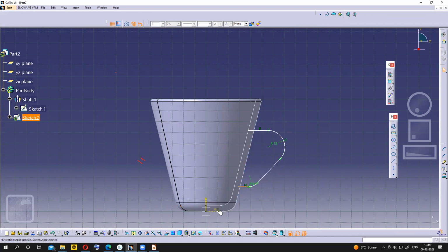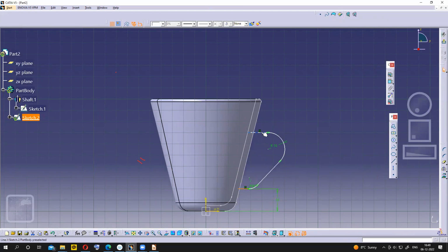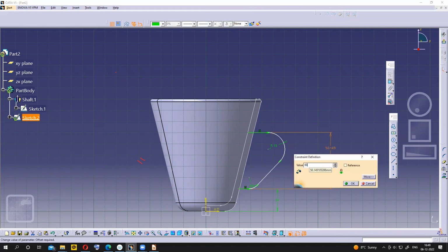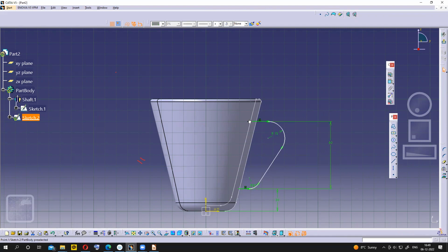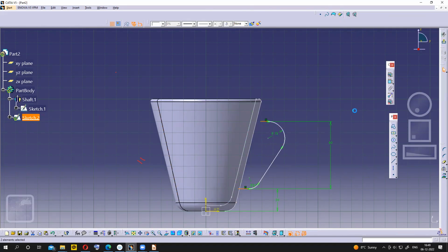Yeah, it's moving a little bit. So from here to here is 20, and from here to here 60. You can keep this one outside, a little bit outside or a little bit inside, no problem. So we can use the merge ribs option checkbox, so that it will automatically extend the rib already.